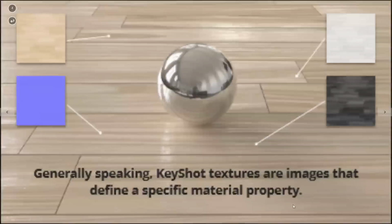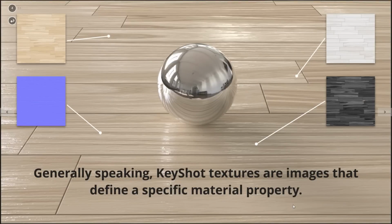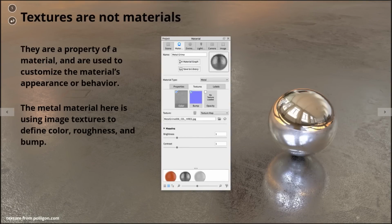Textures in KeyShot are generally going to be images that define some sort of specific material properties. So in this case right here, we've just got a simple chrome sphere, no textures on it, and it's sitting on top of a ground plane. And that ground plane actually has a material applied to it. So we're using images in order to define something on that material. We can use them to define the color, for example, or the way the light bounces off of them, or things like roughness. Textures are not materials, they are a property of a material.